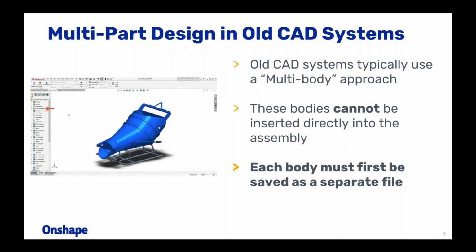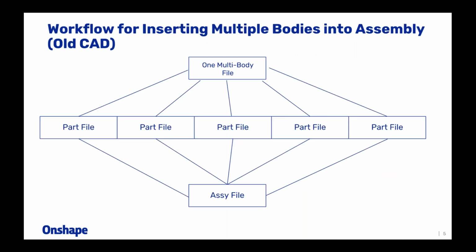So it's somewhat of a tedious process, something that arguably you could say is one of the biggest downsides to multi-body modeling, right? The need to export everything before you can insert it into the assembly. So that's one of the biggest things that I would stress about multi-body design and these similar approaches in old CAD systems. And as I mentioned before, this creates kind of this web of files that really is troublesome to deal with, and it makes things like updates confusing.